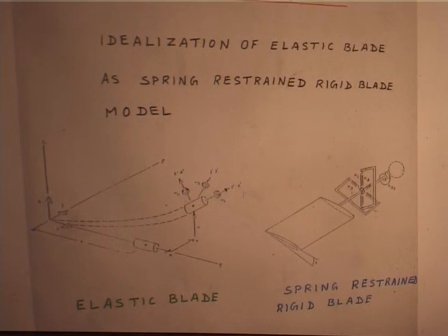A rotor blade has infinite modes because it is a continuous beam, but for practical analysis, from the design point of view, usually for flap you take about 3 or 4, lead lag 2 or 3, torsion 1 or 2. Usually 3 flap, 2 lag, 1 torsion. Some people may say, okay, I will take 4 flap, 3 lag, 2 torsion and 1 axial. We take 1 axial mode because that has to bring in some effect.